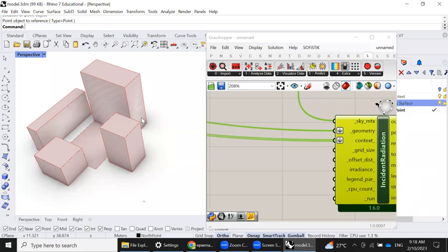And if your site is modeled in mm, it's going to have like a 1,000 times more material to calculate, which is a common reason why a lot of people, when they first try to use Butterfly, get very discouraged because it takes a long time and they think that it's not very effective, but more often they did not set the correct units.